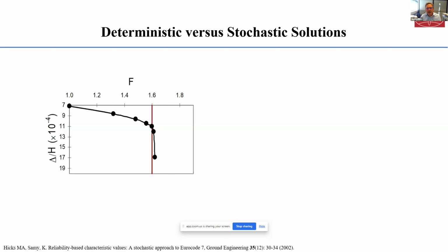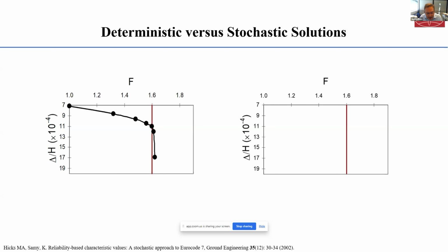safety of the slope. So in this particular example, if we just analyze the slope taking into account the mean properties of the slope, the factor of safety that we calculate is 1.6. And because it's a very simple problem, it agrees with an analytical solution. If, however, we carry out the same analysis, but now we take account of the spatial variability superimposed on top of the underlying mean trend for the undrained shear strength, what we find is we will get a different response. In this case, the factor of safety that we compute is only 1.45.